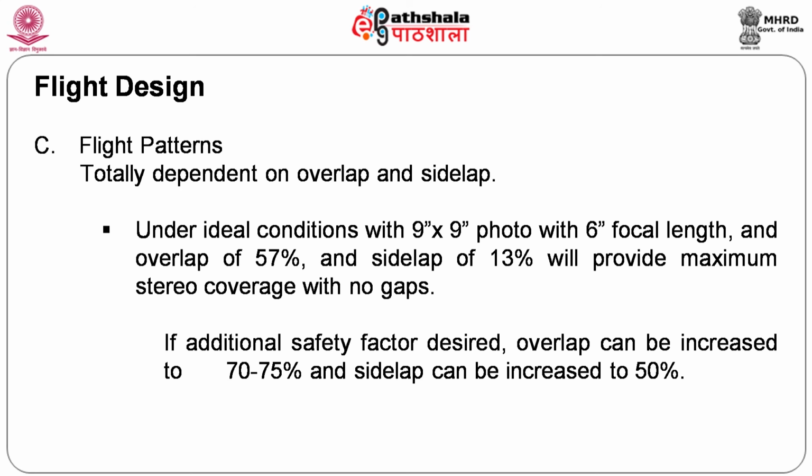Of course, if it is required, you can also go for an overlap of 70 to 75% and a side lap of 50%, but this will increase the number of photographs. So, if you decide, okay, this is what I am going to do, this is how I am going to work, I will have to decide what the side lap and the overlap are.